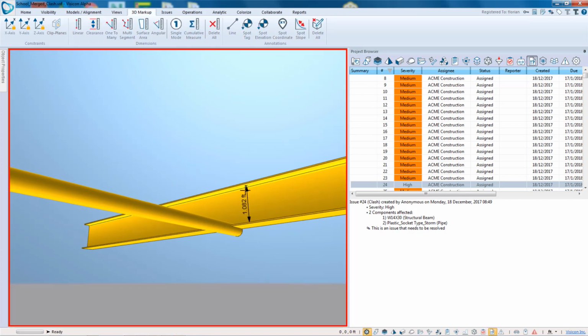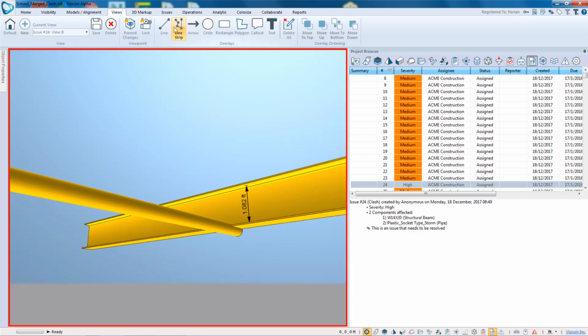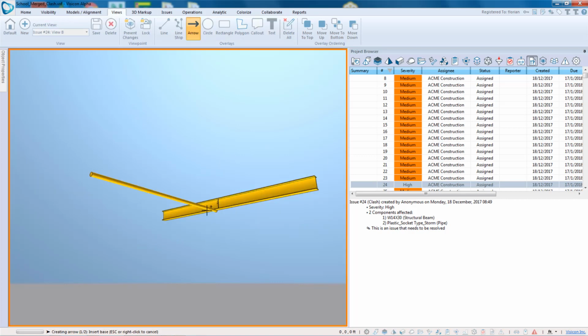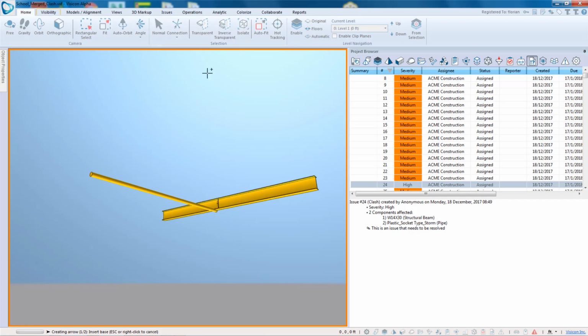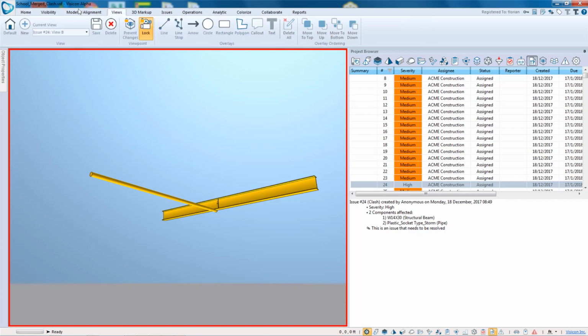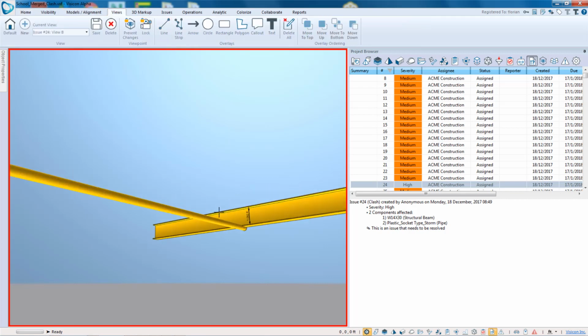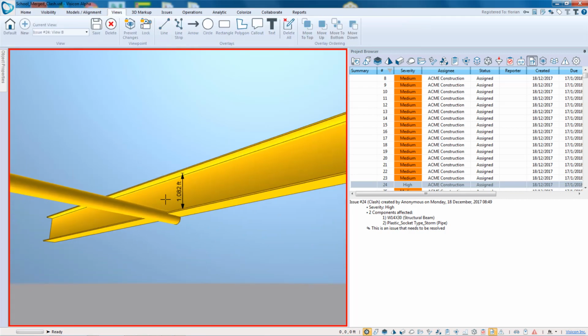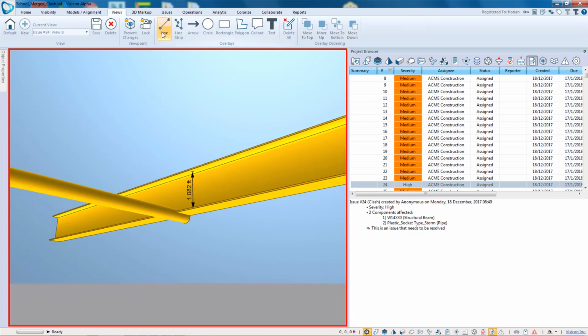So here I give it a 3D markup, give it an additional, okay, it keeps resetting because I have my auto fit set on. So I'm going to go to my view, unlock the view so that I can reset this view and come in, and I'm going to re-lock the view. So essentially that's just locking the camera position.